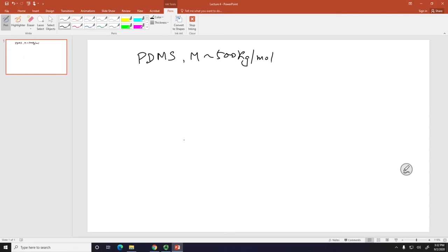So this is a first impression you may gain in terms of what viscoelasticity is. If you leave it for a while, under gravity it will start to flow, given enough time. So the contact time, if you like to guess about the tau in this PDMS, is very short, because my contact time to the table is a fraction of a second. If your internal time is much longer than a fraction of a second, that molecule cannot move. And that's why this PDMS looks like a rubber ball.